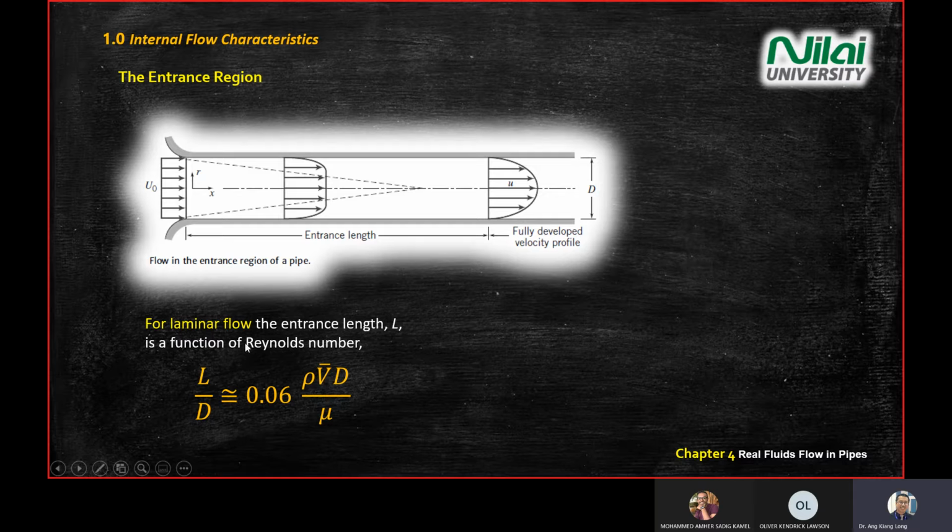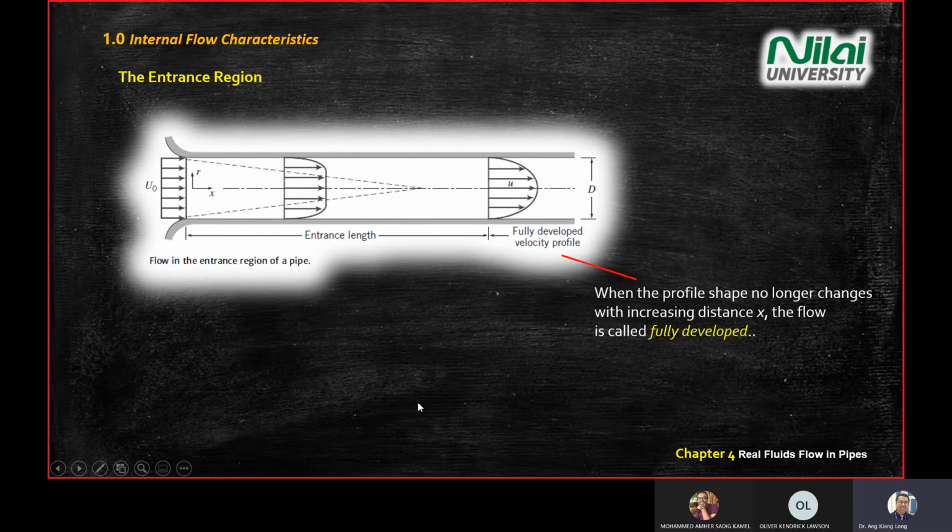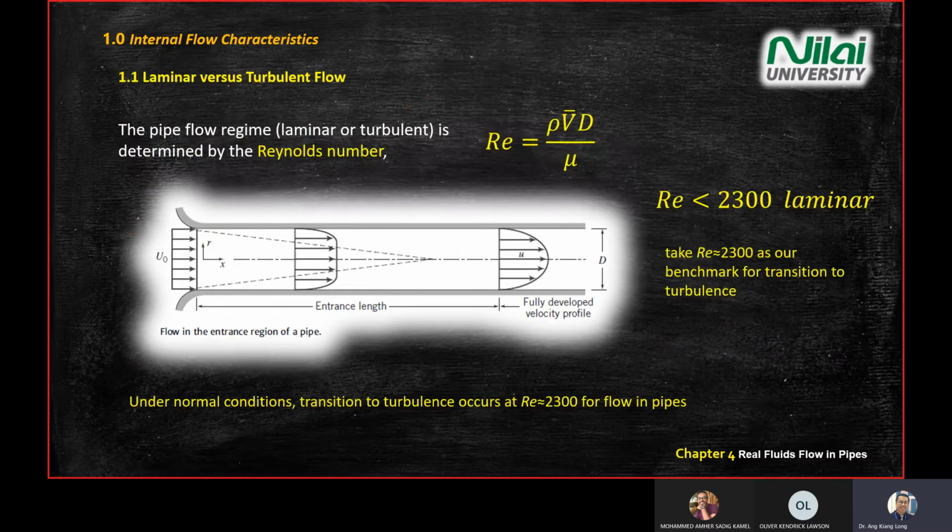Okay? So there are two ways to know what type of flow you have in that pipe. One, through Reynolds number calculation. Second, through the length and the D that you have. So the first equation, Reynolds number: how do we ask you a question in the exam? After you calculate, the rho you can find in Appendix A.